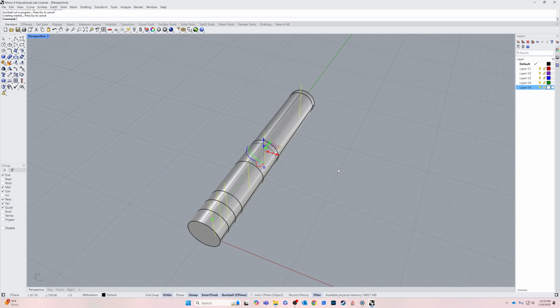Another thing that's cool about that split, that cut tool that we've got is it automatically caps these objects off so that they're solid objects here. Let's go back. I want to show you the difference real quick. So I'm going to go to a right view here. So the old school split this object with these objects, enter, and then I go back to perspective here. And yes, it does split them, but it leaves them hollow. So it's a much better tool to have that cut option there. So kudos on Rhino 8 there.